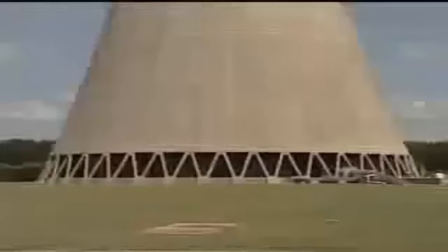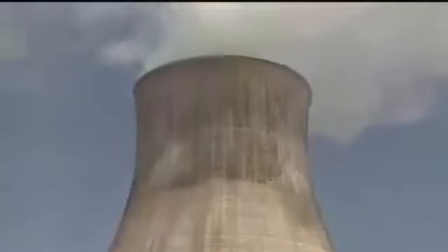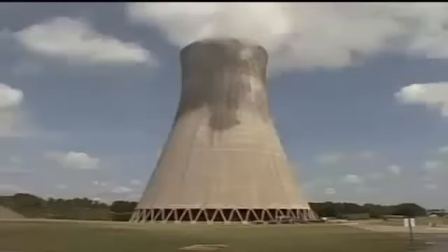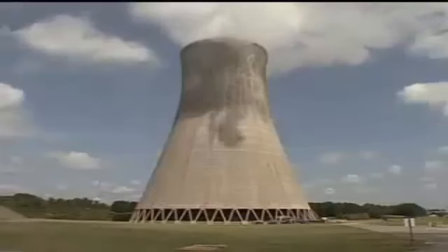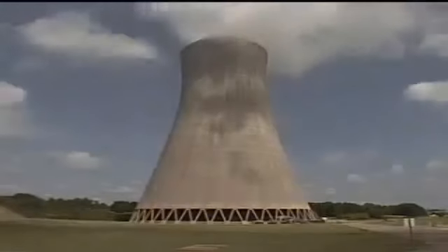In a natural draft cooling tower, the warm circulating water is splashed over tray-shaped baffles. This spreads the water over a large surface area. The flow of air through this area cools the water by convection as well as evaporation. During this process, the air is heated and begins to rise. The chimney design accelerates the flow of air up through the tower and thus increases the overall airflow. Atmospheric pressure pushes more air through the tower to maintain the airflow that cools the circulating water.